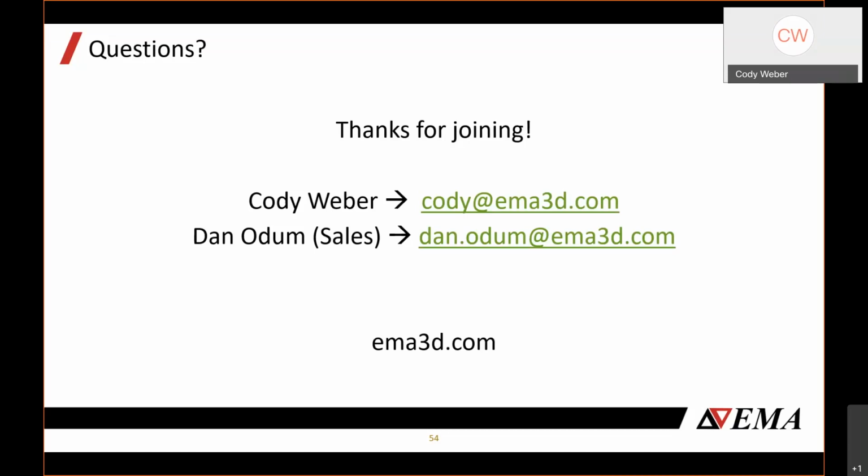All right, and then we have one more question from Edward Barnes. He says, does EMA3D Cable work for lightning indirect effects too, or is it a different software package with the same model? Good question, Ed. It's the same. When I say that you can use the same model for HIRF and indirect effects, it is just a different source application. In the case of HIRF, we're using a plane wave illumination, a Gaussian pulse with a certain frequency cutoff.